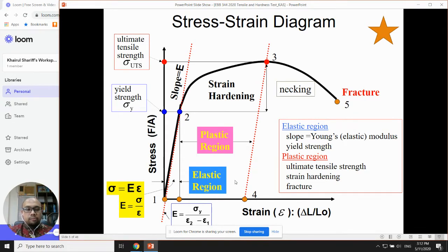What I want to touch on in this part is, as I mentioned earlier, that in this stress strain curve we have three stages. Number one, when you do the tensile test, as you can see in the first video, we pull the metal rod, or metal dumbbell shape sample, in opposite directions. The measurement will read the stress and strain constantly increasing. Meaning that if you pull and the reading increases, you already know at the initial stage this metal is a ductile type metal.